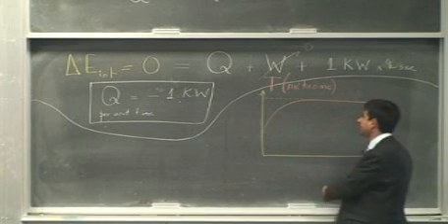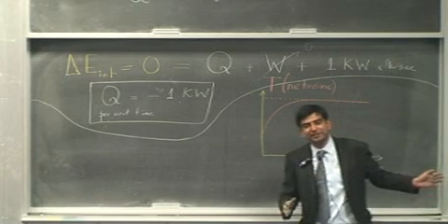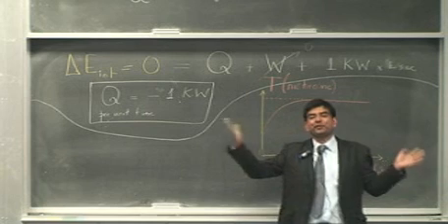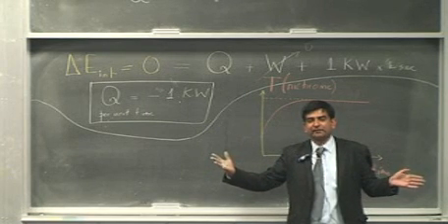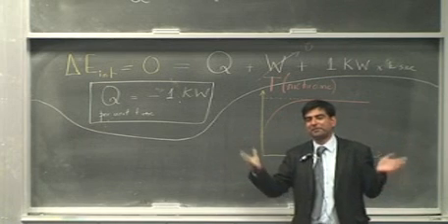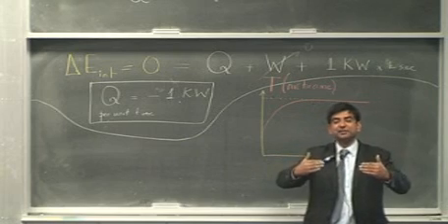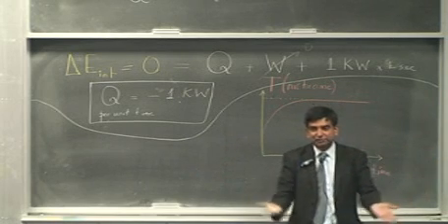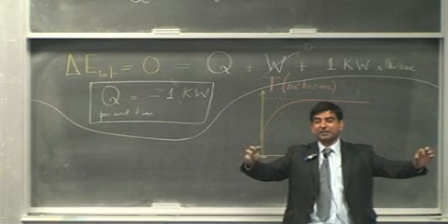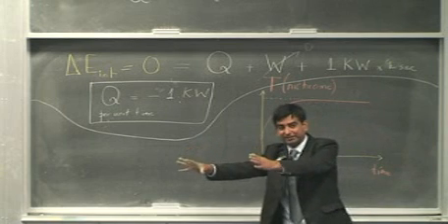So this question is dealing with a steady regime. If electrical energy keeps flowing and the internal energy keeps increasing, you will eventually have a small sun in your room because the temperature is going rapidly up. But the temperature is stabilizing because there is energy transfer to the environment. As soon as the heater heats up, there is a large temperature gradient between the nichrome and the atmosphere, so the heat losses increase.